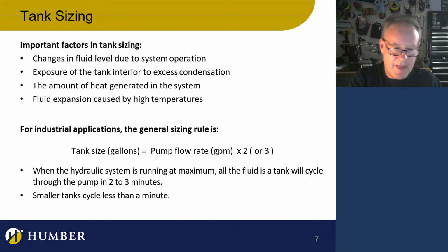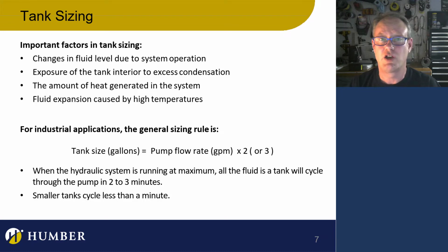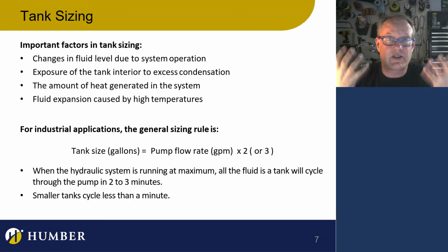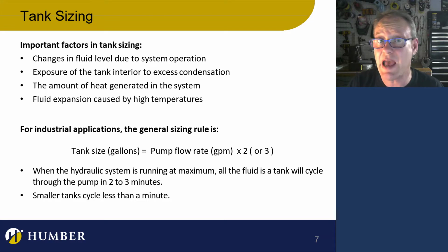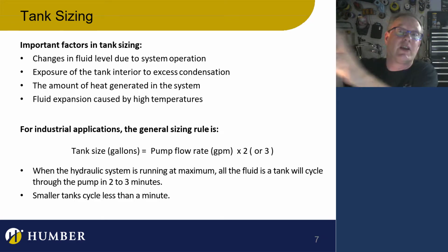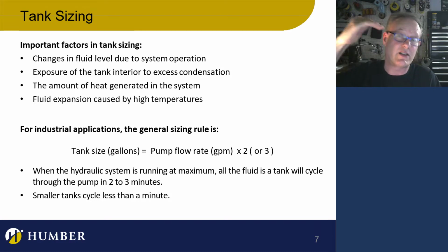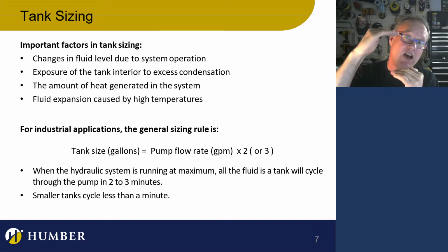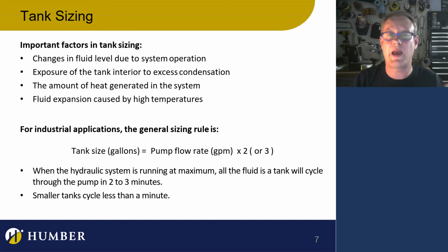Actuators extend and retract, extend and retract, and there's a certain amount of heat generated there, but certainly motors generate a lot of heat. So we've got to get rid of that heat. Hydraulic oil can also expand. So we have to make sure our tank not only has the ability to handle all of the fluid that's leaving and going into the system and still staying high, but we also need enough space in the tank for the fluid to expand and for foam to be generated on top, which does happen. So we have to think about all of these considerations when choosing a tank.